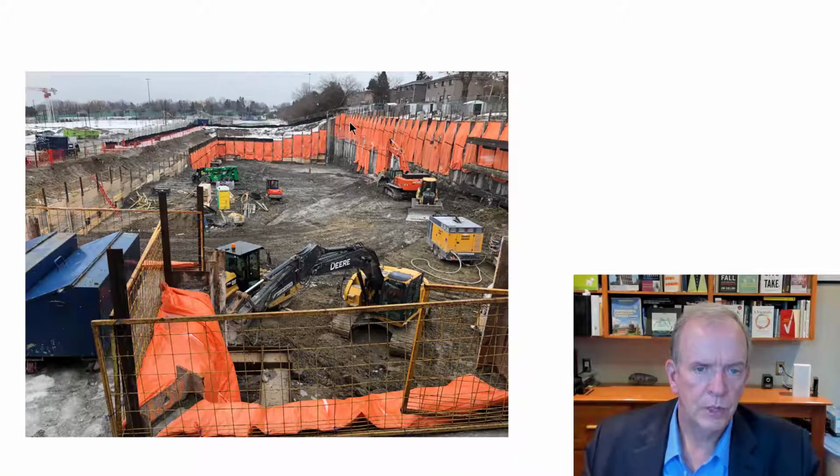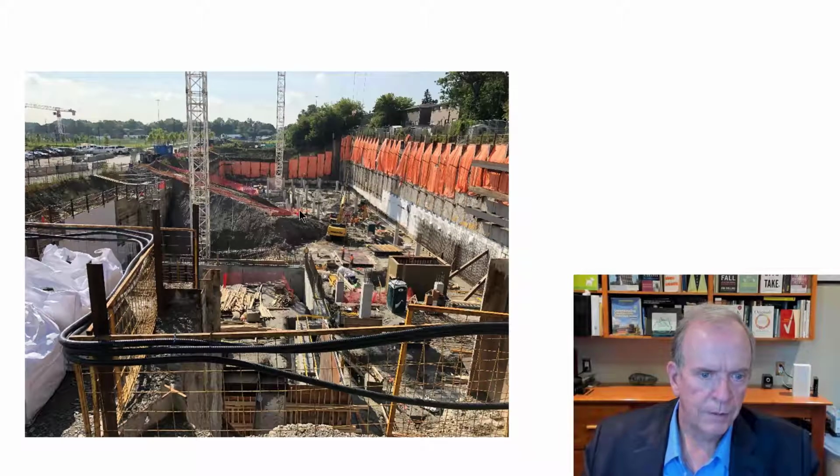And now as the work goes along, you can see the pilings are in place, the excavation is going deeper. Things are set up down the side again with the shoring on both sides. The lagging is being filled in as the excavation goes deeper and deeper. Then you've got a ramp. This is being removed now, but they had a ramp so they could get equipment and various things down to the bottom. So they built this ramp down here, whereas before it wasn't even there.